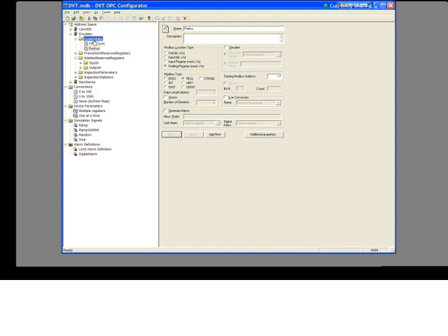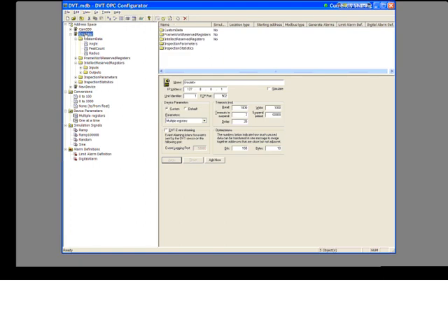Okay, and then I'm going to add angle here. The angle is also real and starts on register 19. Okay. Now going back to device parameters, notice that instead of the default device parameters, we have selected custom, and we have selected multiple registers.